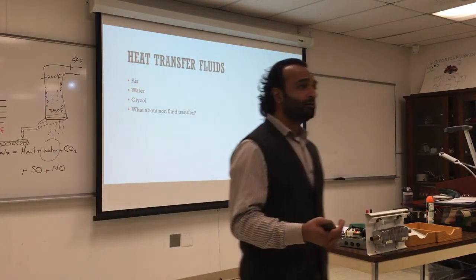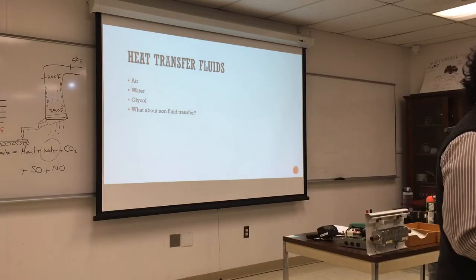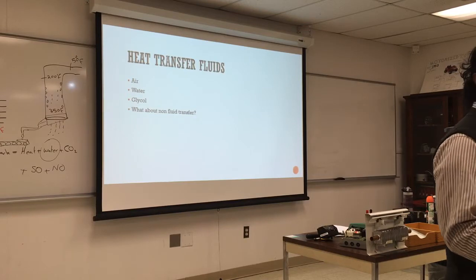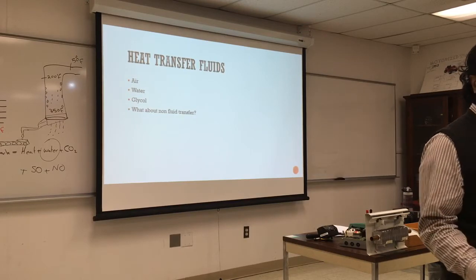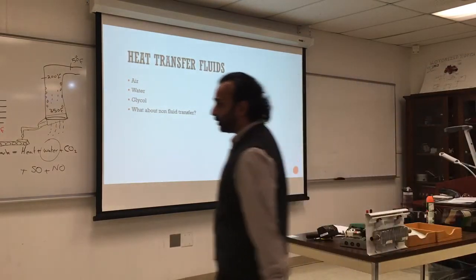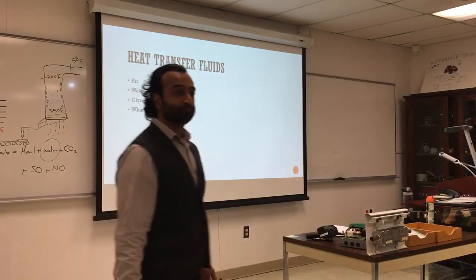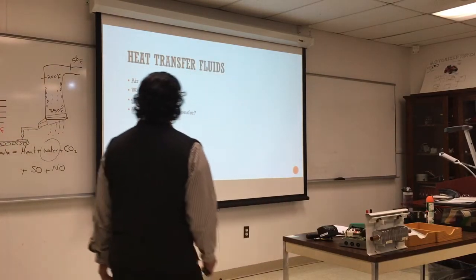Sometimes they use water, because you have a leaky radiator, you keep adding water to it. If the water becomes too much, water will react with the engine and you have a lot of rust coming out. If you drain one of those boilers, usually there's a drain here, so you can change the water, it comes out very rusty. So that's another issue. That's a bottom blowdown, right? Yeah, blowdown system. Yeah.